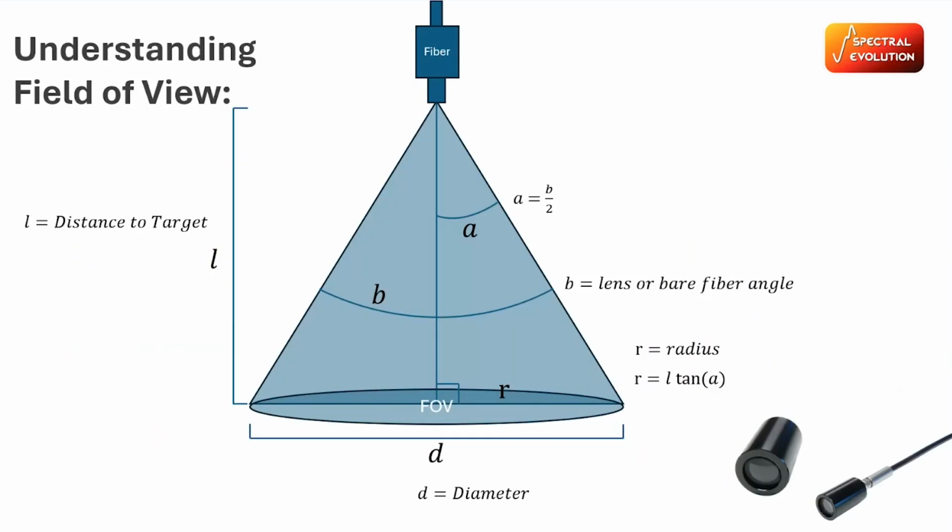So with our instruments, we're able to easily change our field of view and govern what size we're scanning. So you can change how big your field of view is at different distances by simply changing the lenses that we have. So we have a wide range of different angle lenses. They can all be radiometrically calibrated to get energy units.